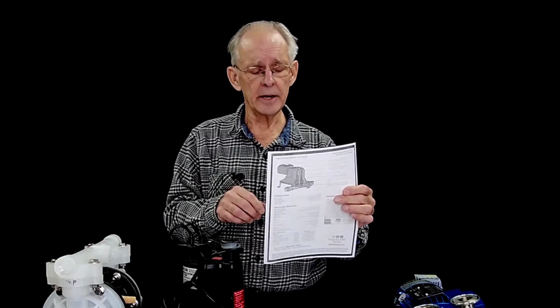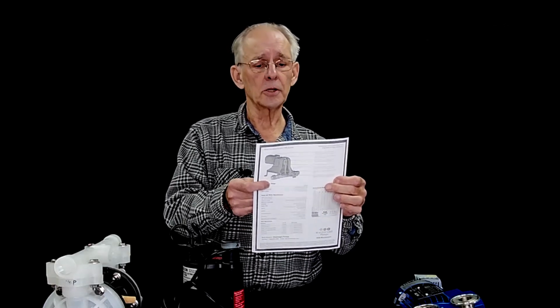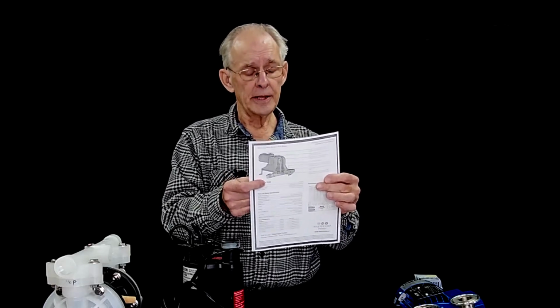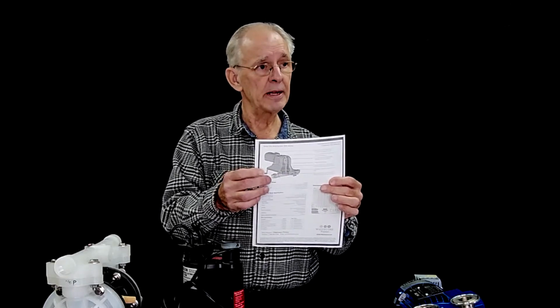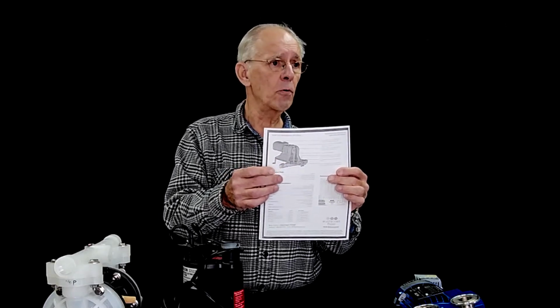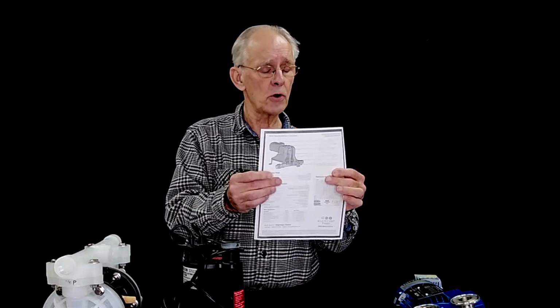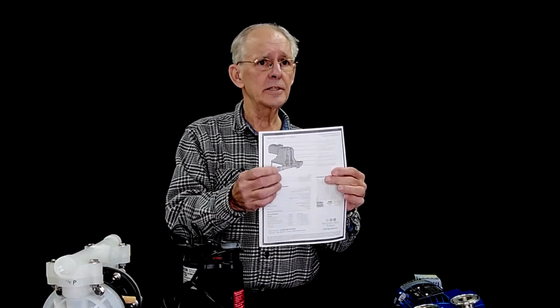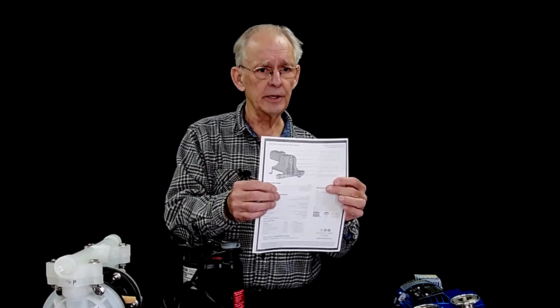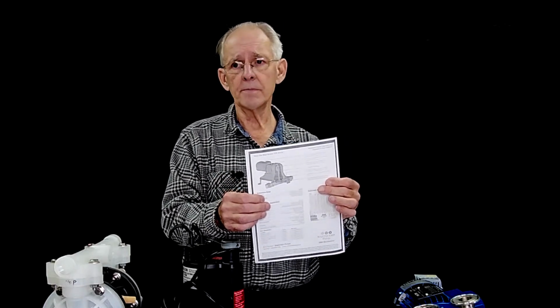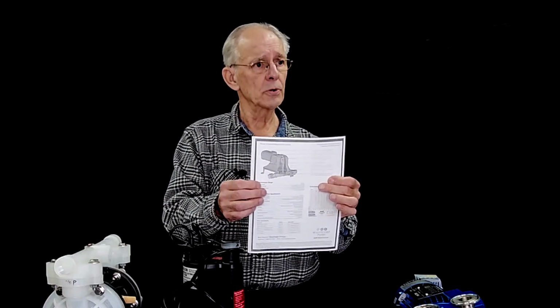So this one is typically used as what they'll call a sucker pump, because they can lift water quite a bit. They're self-priming, meaning that you don't have to put water in them to start them. They'll start from dry. And they're used to dewater pits and things like that. And we've used them in waste treatment for bringing in raw sewage.